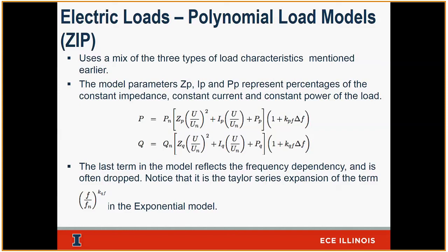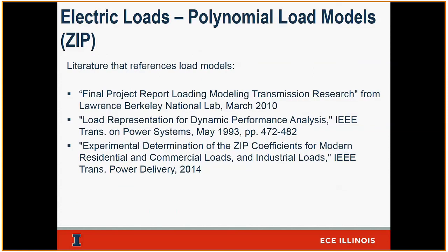And they will change the voltage. They'll make it 125, right? And as you change that voltage, they will see how that changes your power consumption on it to better, again, understand what your Z and I and P components are. And they experimentally figured out each one of these components. So this truly can reflect, at the end of the day, what the expected behavior of each component could be, and then you aggregate those to, again, put them in more of a residential or commercial or agricultural type model.